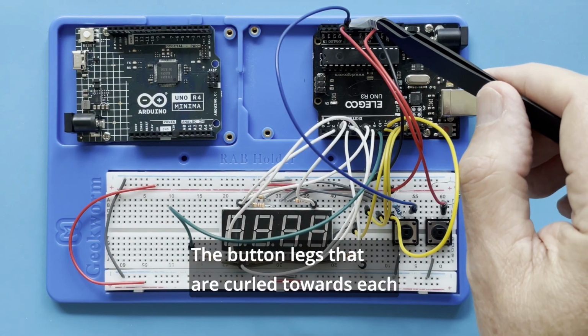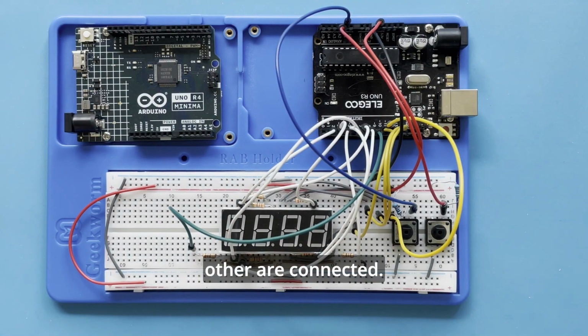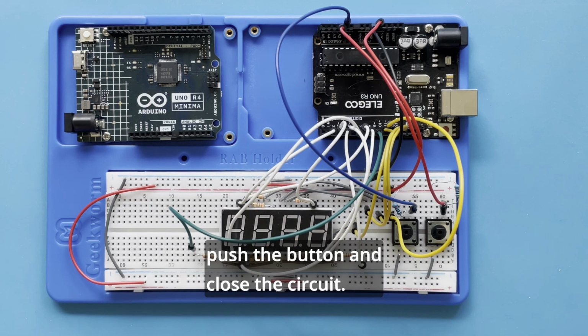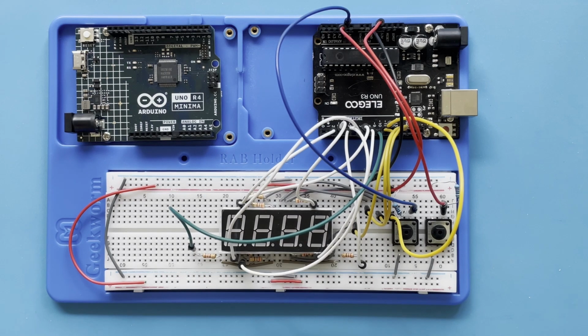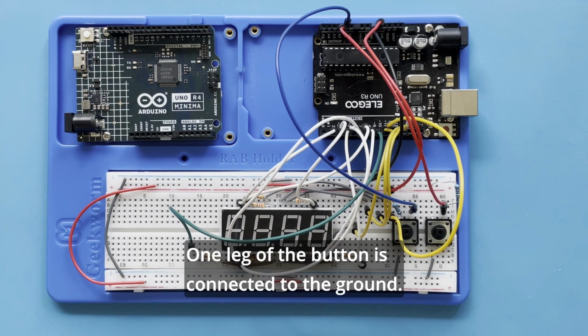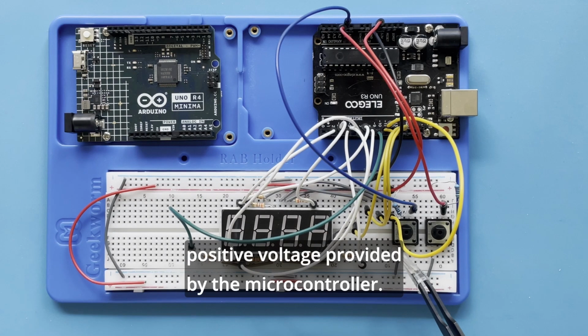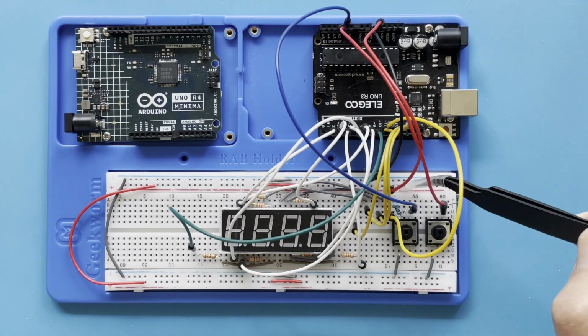The button legs that are curled towards each other are connected. The other legs are not connected until you push the button and close the circuit. One leg of the button is connected to the ground. The other leg is connected via the pull-up resistor to the positive voltage provided by the microcontroller.